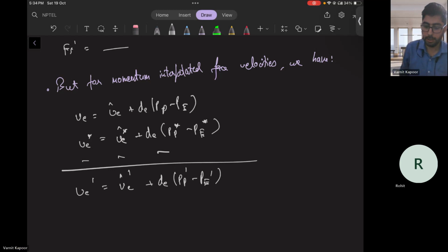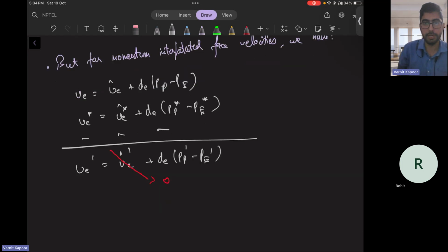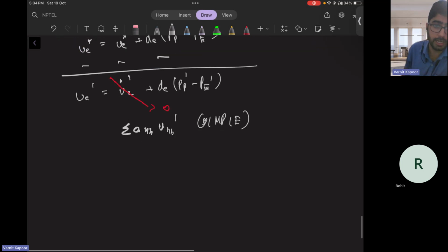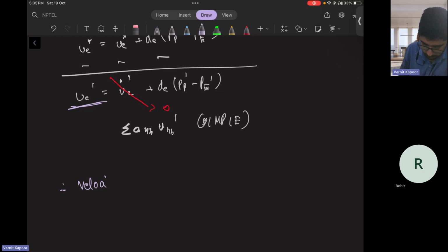And this term, the contribution from the neighboring terms, will be 0 as per SIMPLE. Okay. We have got the velocity corrections. So your velocity corrections are U prime and V prime, and similarly for the other phases.